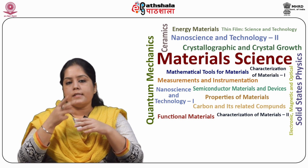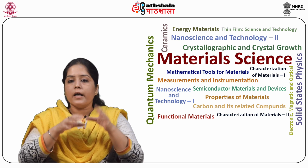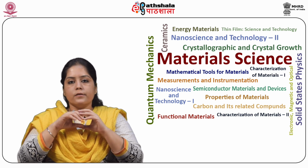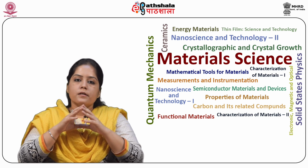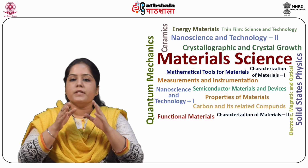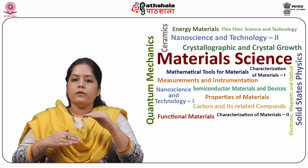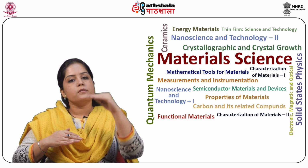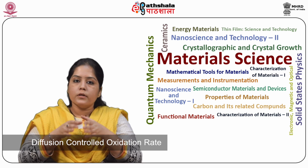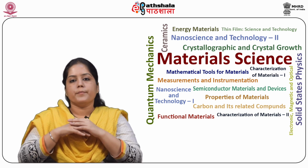Now consider the second case, the introduction of higher valence metallic ions in the oxide. In this case, the concentration of interstitial metallic ions decreases and the number of excess electrons increases. So the diffusion controlled oxidation rate overall decreases.